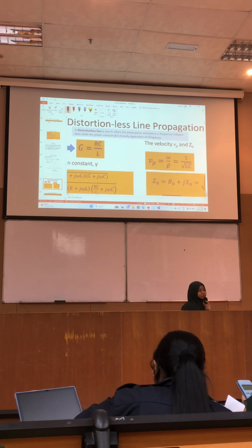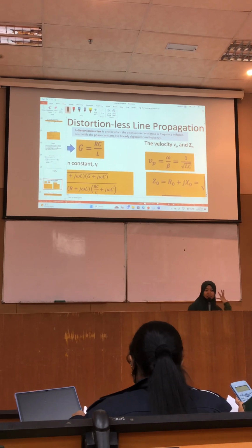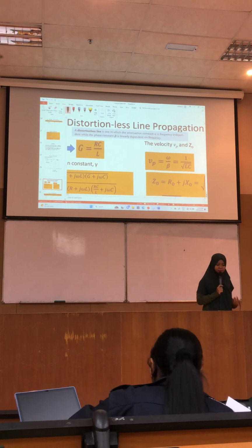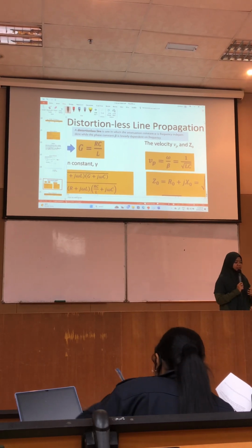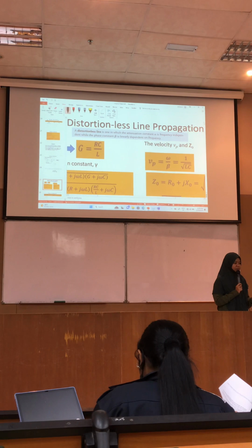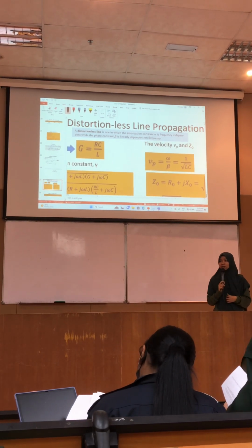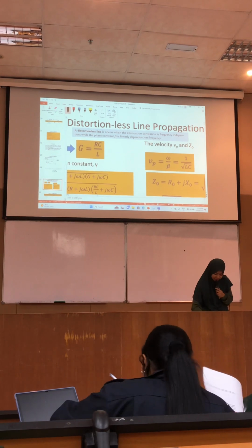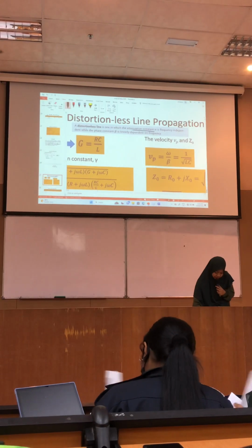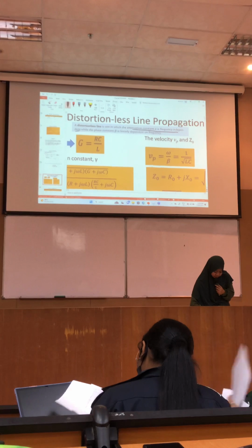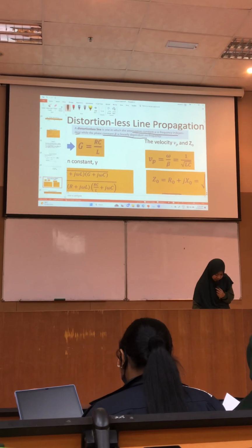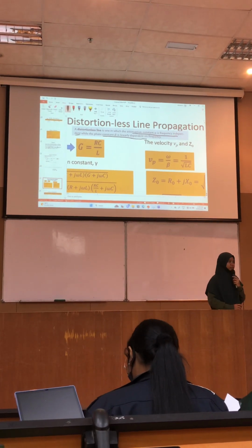Distortionless line is basically the same but not equally the same as lossless line. Okay? Distortionless line, attenuation constant is frequency independent. Phase constant is linearly dependent on frequency.